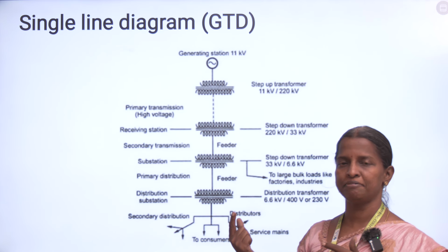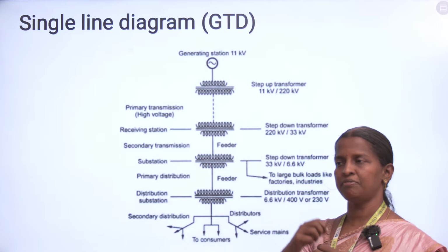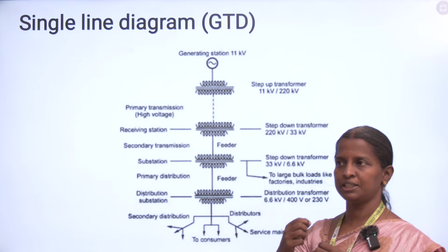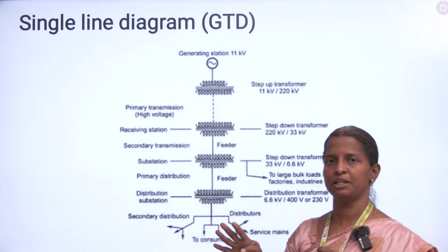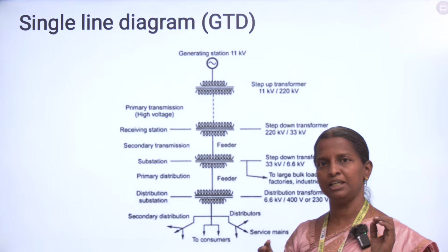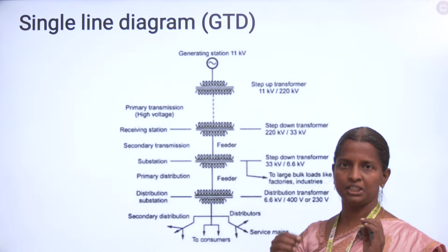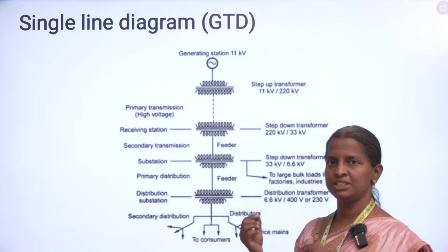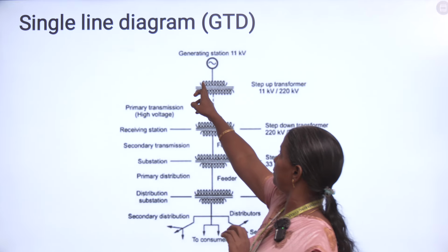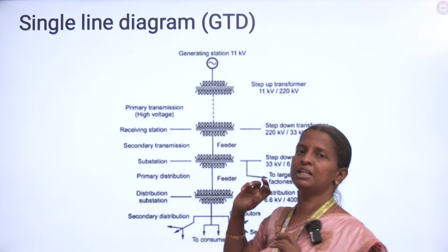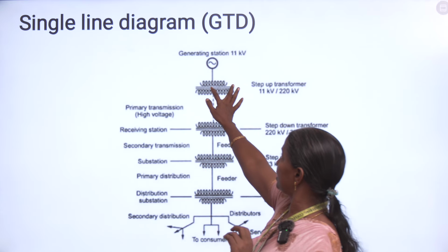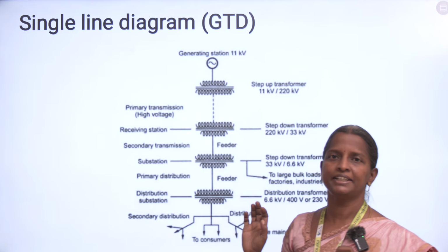Mostly it will be made up of copper, and we will start the winding. First, for example, I am taking the primary winding with 40 turns. The start will be on the outside and we will wind the 40 turns. At the end we have to take it outside. So these are the 2 terminals here. The primary winding will have 2 terminals, and to those we will apply the voltage of 11 kV.